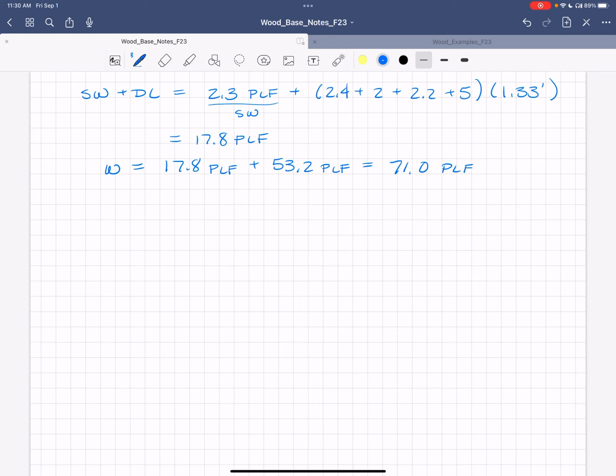So now I'm doing flexure, so let's figure out our moment. Moment for these, we assume these are simply supported, WL squared over 8, right? Or go do statics if it hasn't been in a while, and the max moment's at the center, and that's the WL squared over 8. At the edges, it's 0. So we're looking for the maximum moment.